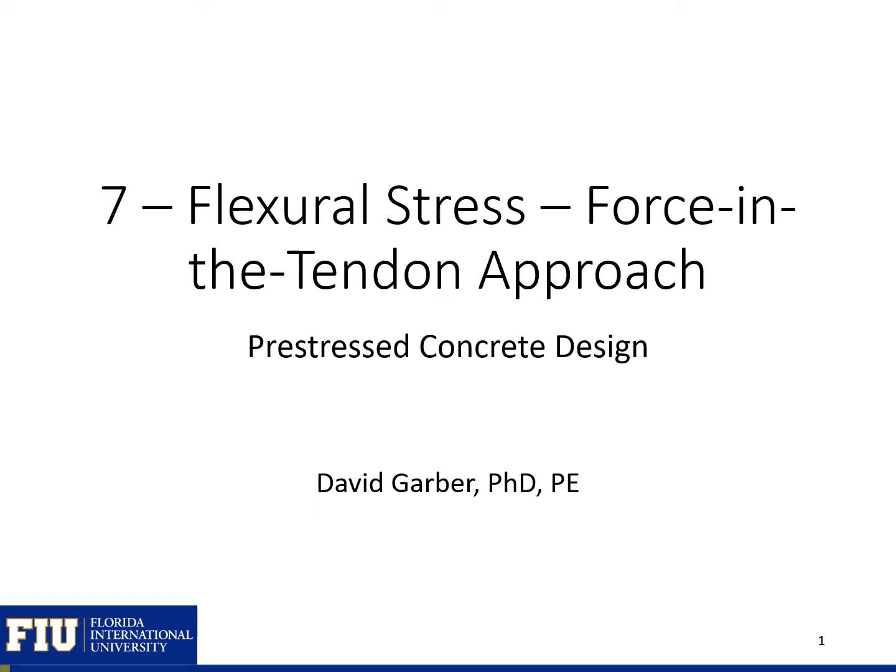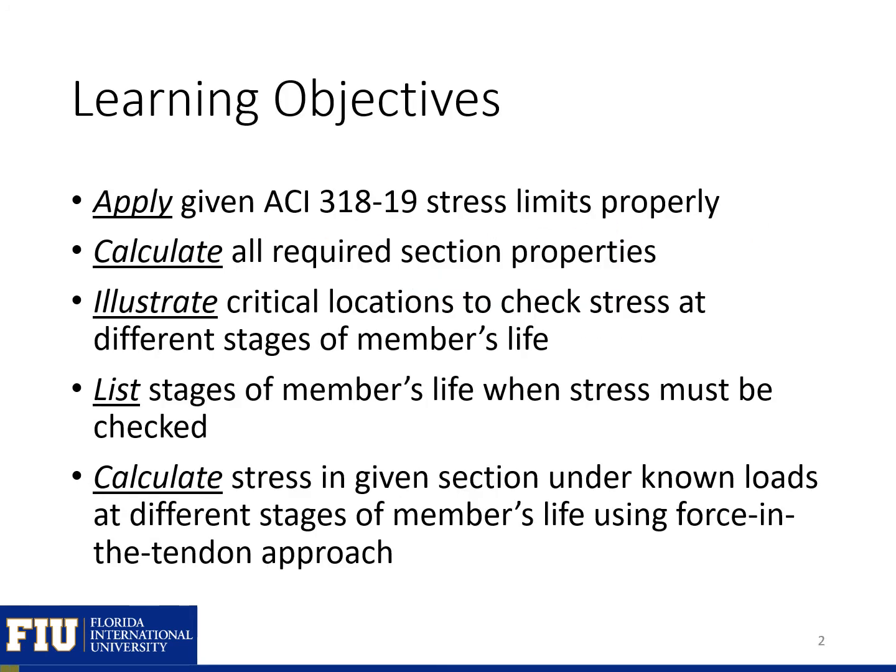In this module, we'll be going through how to calculate flexural stresses using the Force-in-the-Tendon approach. By the end of this module, I want you to be able to apply the given ACI 318 stress limits properly, calculate all required section properties, illustrate critical locations to check stress at different stages of the member's life, list stages of the member's life when stresses must be checked and should be checked, calculate stress in a given section under known loads at different stages of the member's life using the Force-in-the-Tendon approach.